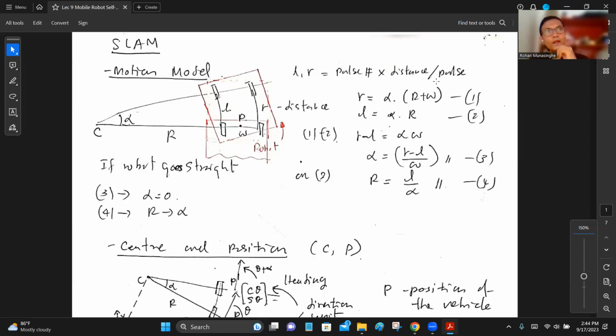So if you read the pulse counter now, you have a certain value, and read the pulse counter after about 10 milliseconds, the pulse counter has changed, and you know by how much. You can put it into this equation and calculate your left and right wheel distances, the distances the two wheels travel on the ground.